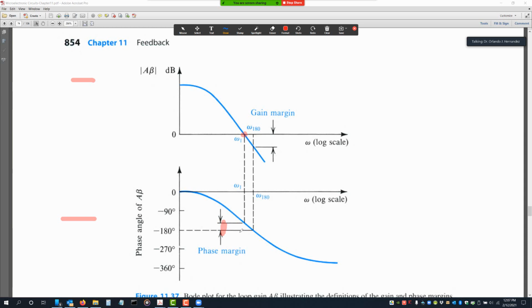What that says is that, again, you want your response to either decay faster, or you want your phase to extend into the higher frequency, which is extending the bandwidth. So extending the bandwidth makes your system more stable, by making your phase margin greater. Because now, if you look at this, the phase margin would be something like this. So feedback, for the purpose of increasing the bandwidth, is a technique of frequency compensation.